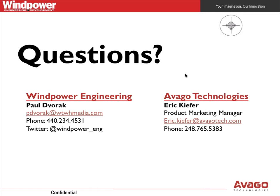We actually do sell plastic optical fiber with that Versatile Link connector, and it's mainly to enable customers who want to use this HP connector, which is what the Versatile Link is. So we do sell plastic. We sell it with Versatile Link connectors, and we sell it with bare fiber. However, we do not sell glass fiber. Those use industry standard connectors like ST connectors, which are still used quite a bit in the telecommunications and data communications industry, so there are plenty of cable suppliers out there that could do that.